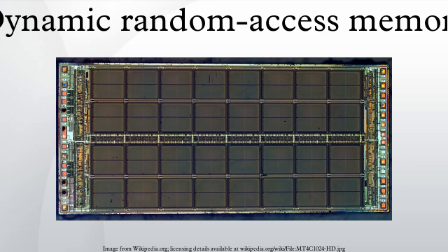These numbers represent tCL-tRCD-tRP-tRAS in multiples of the DRAM clock cycle time. Note that this is half of the data transfer rate when double data rate signaling is used. JEDEC standard PC3200 timing is 3-4-4-8 with a 200 MHz clock, while premium-priced high-performance PC3200 DDR DRAM DIMM might be operated at 2-2-2-5 timing. Minimum random access time has improved from tRAC = 50 ns to tRCD + tCL = 22.5 ns,